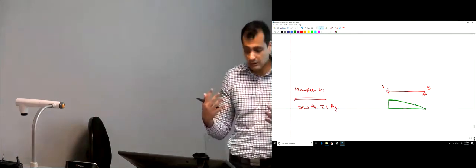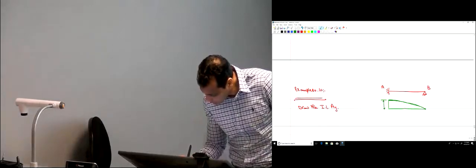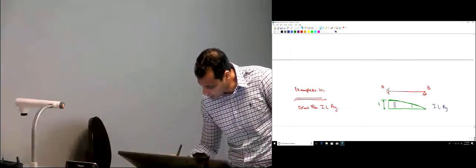An indeterminate beam is a beam with more supports than actually needed. That's why it's always going to be curves here. So this displaced shape represents the influence line of AY. It's positive like this, but it's a curve. So this is an important remark.